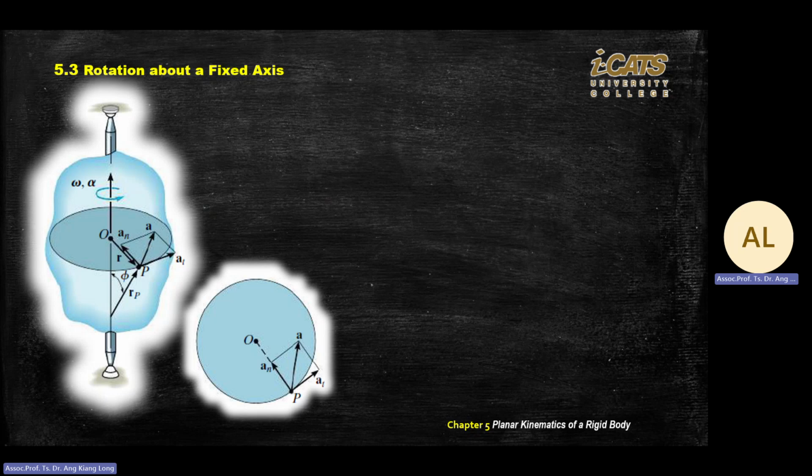In a rigid body, the normal component of acceleration always points inside, towards the center, when you rotate something. And the tangent component is parallel to the velocity direction, along the tangent. Because this is a vector, you have n and t, then you have the resultant of a. How to find the resultant? You use trigonometry, the square root of an squared plus at squared.